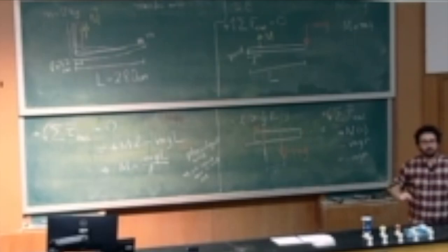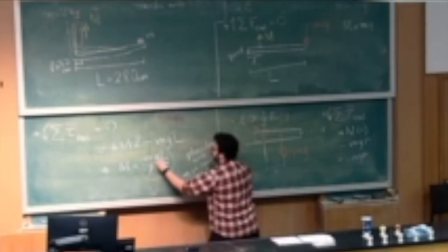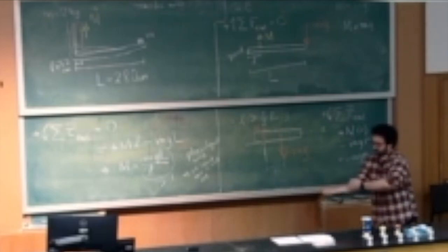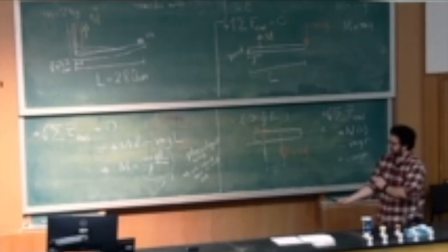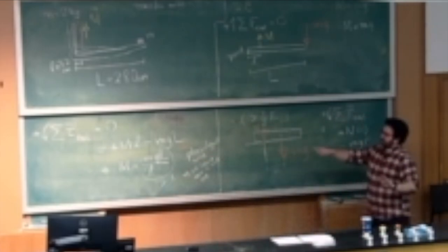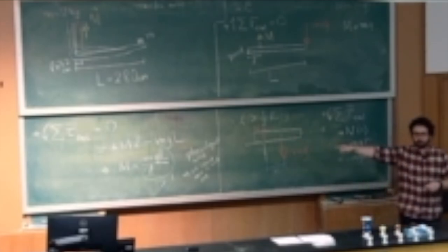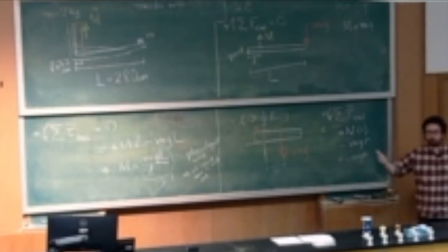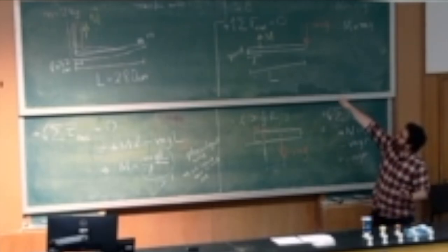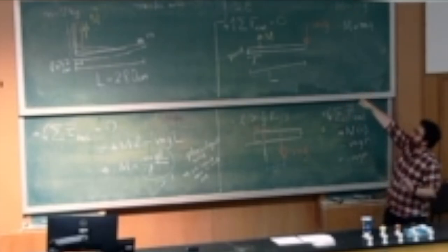Yes. One more time. So this factor is certainly greater than 1 because capital L is this distance and lowercase l is this distance. It is the distance of the muscle from the elbow joint. With this, capital M, that force in the muscle, is larger than mg because that factor is larger than 1. Say it is 2, or we can compute it, actually it's close to 10. So we have this upward force M, which is a lot greater than mg.